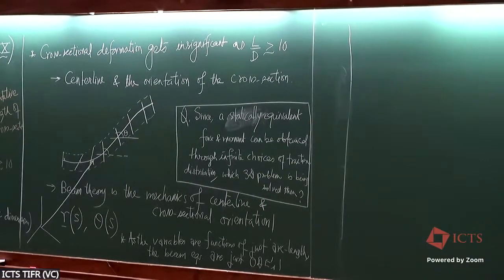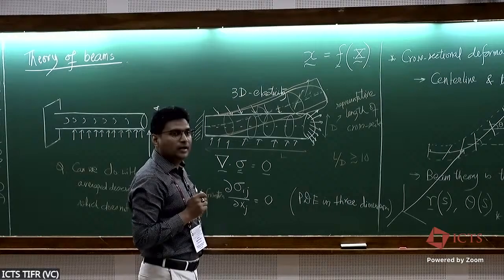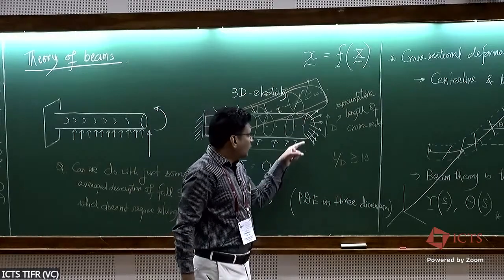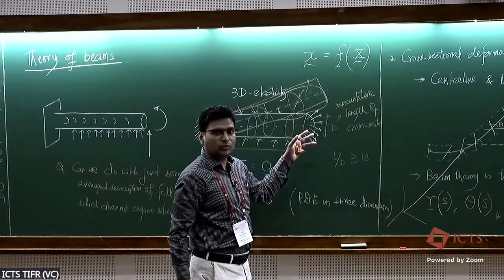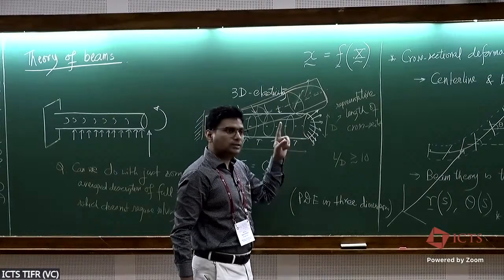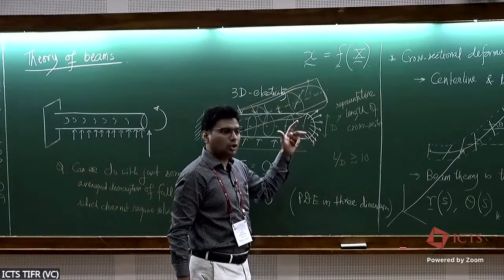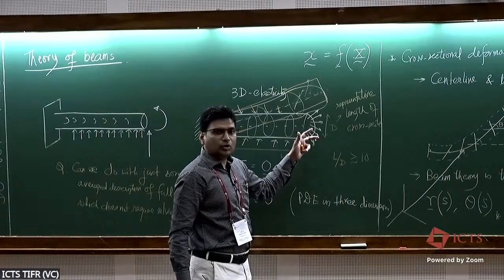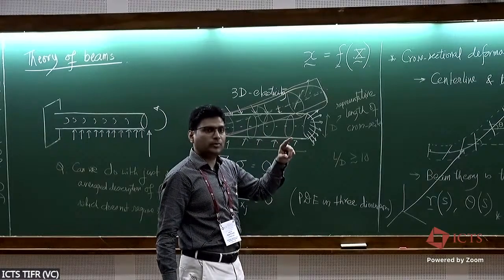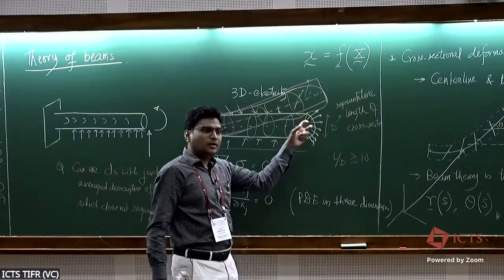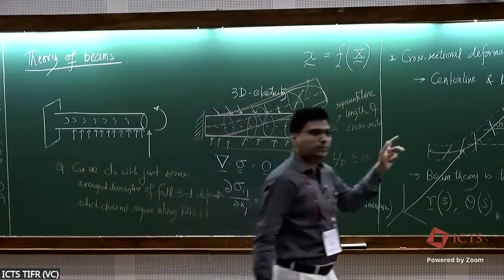But fortunately, there is a very interesting principle, the Saint-Venant principle, that comes to our rescue, which says it doesn't matter what your traction distribution is. If all those traction distributions lead to the same resultant force and moment, or if the traction distributions are statically equivalent, then the 3D solutions will start to match for different traction distributions as you go away from the point where the traction distributions are acting. So the Saint-Venant principle comes to our rescue, which says